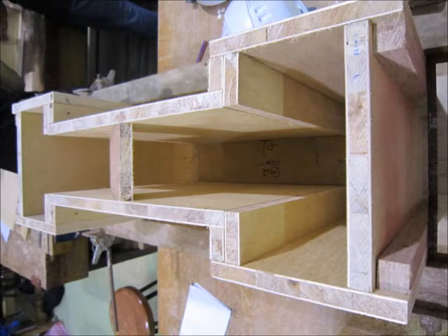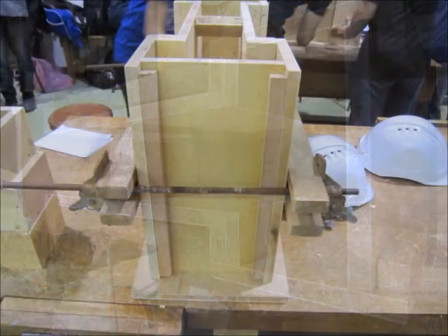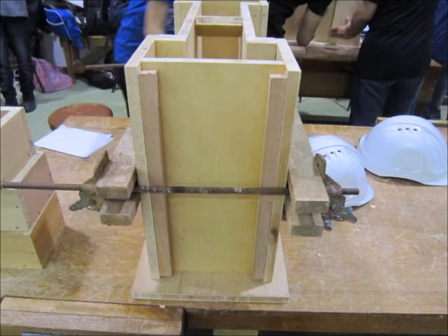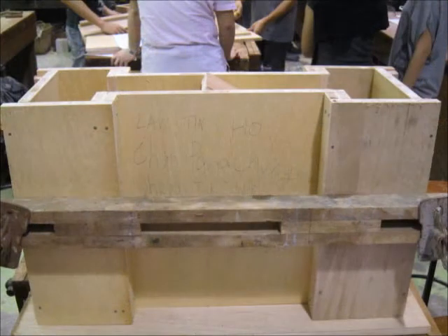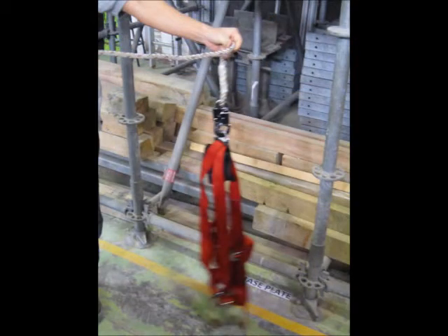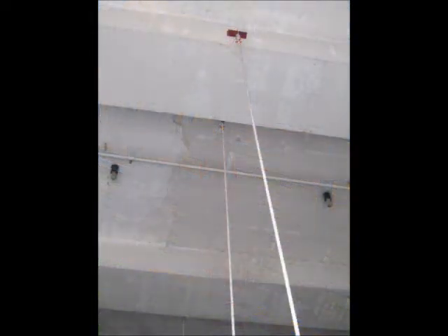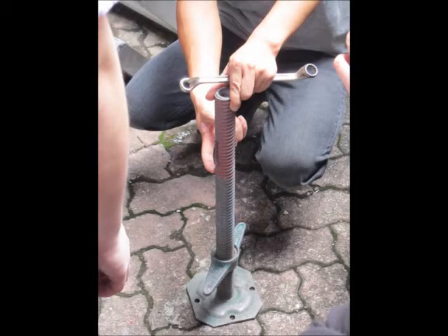In falsework and scaffolding training, we were required to erect two one-storey scaffolds. We used the materials provided to erect the scaffold according to the provided drawing. First, we place the screw jack base on the corners and put the walk-through frame on the base. Fix cross braces to the flat lock on the walk-through frame.